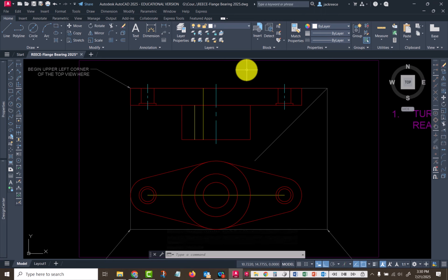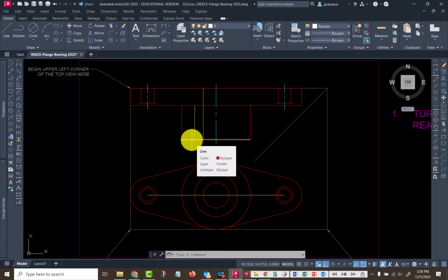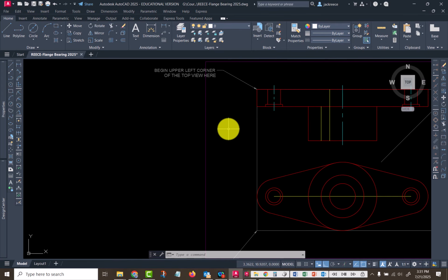All right. Now we don't know the depth of this thing because it tells me that the countersinks are at an angle. It's an angle of 82 degrees. Well, that's the inclusive angle between both sides. So the inner angle, let me come over here to the side and I'll show you. So if I draw a line and a line, those lines are perpendicular. Now I know this thing is at 82 degrees, so half of that is 41 degrees.